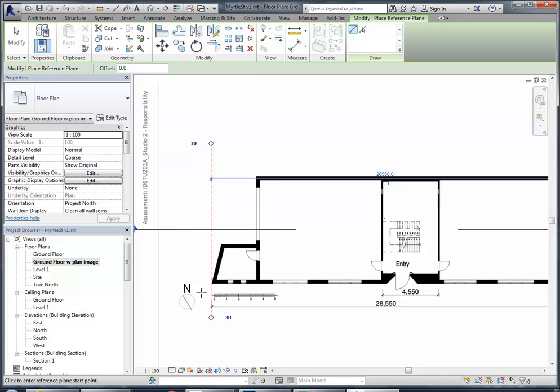Pretty much, yeah. If you get from AutoCAD, then it's even faster because you can just draw straight onto the AutoCAD lines. But if it's an image, yeah, it's good to put these in, because if we just draw straight over the image with walls, then we'll end up with all sorts of odd numbers. So the reference planes should help with that.